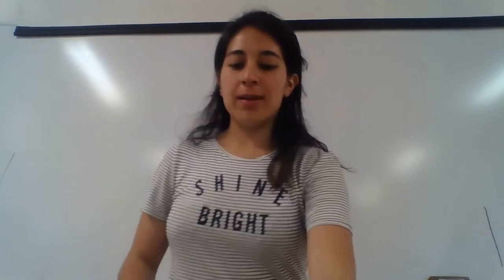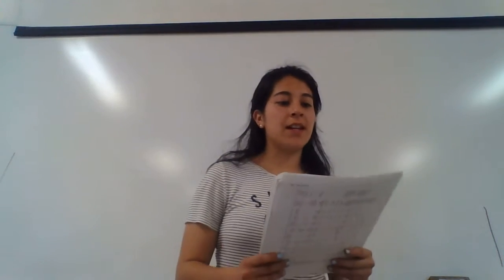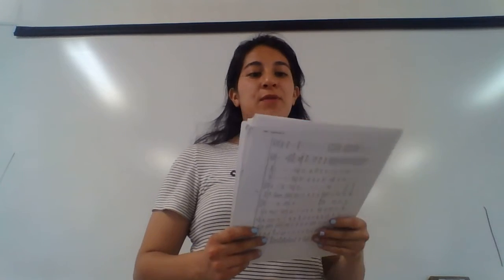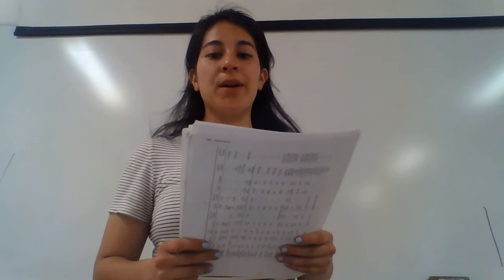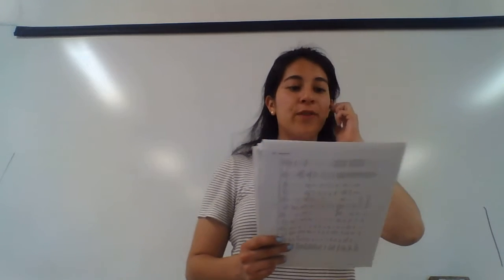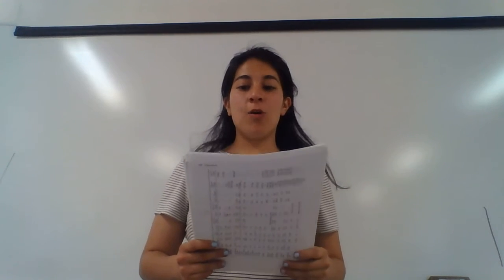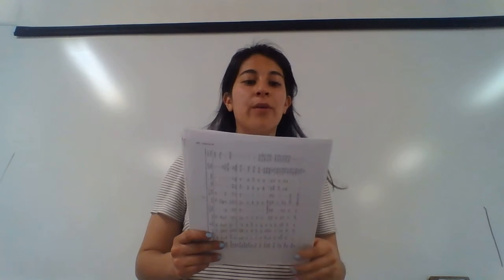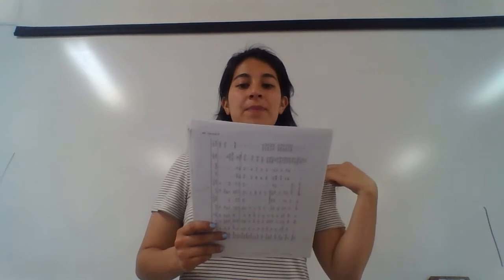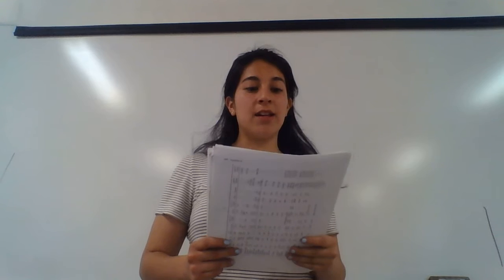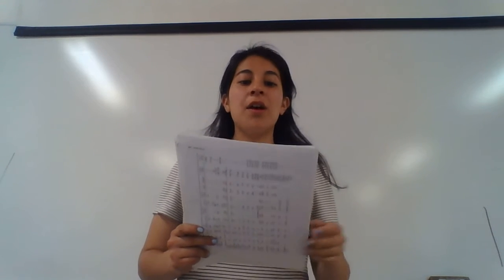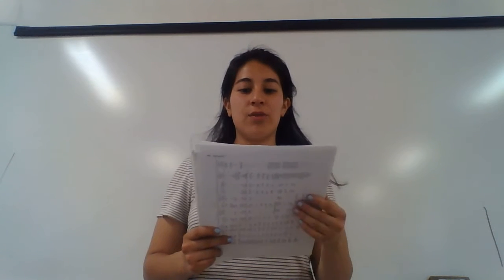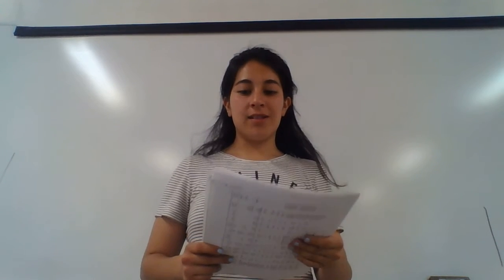So for this problem, we have that a student living in a 3 times 4 times 4 meters dormitory room turns on her 100 watts fan before she leaves the room on a summer day, hoping that the room will be cooler when she comes back in the evening. Assuming all the doors and windows are tightly closed and disregarding any heat transfer through the walls and windows, we have to determine the temperature in the room when she comes back 8 hours later.